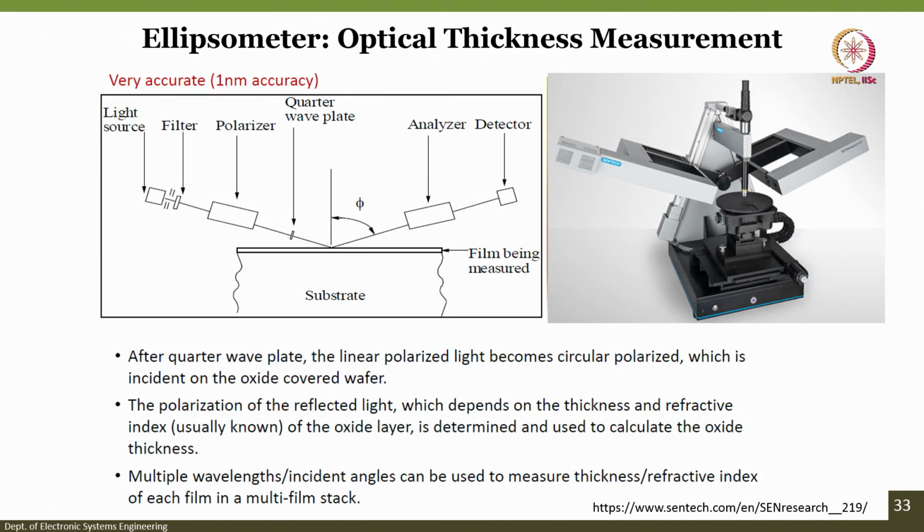So, with this we will stop talking about the oxidized silicon wafer or the thermal oxidation technique, and how we can measure the thickness of silicon dioxide using a surface profilometer or using an ellipsometer, right, what is a destructive technique versus a non-destructive technique, how the colors change depending on the thickness of silicon dioxide, what is wet oxidation, what is dry oxidation, what are the horizontal tube furnace and the vertical tube furnace, how the wafers are placed inside, and what kind of atmosphere should be there, whether it should be nitrogen or oxygen or oxygen and hydrogen, right.